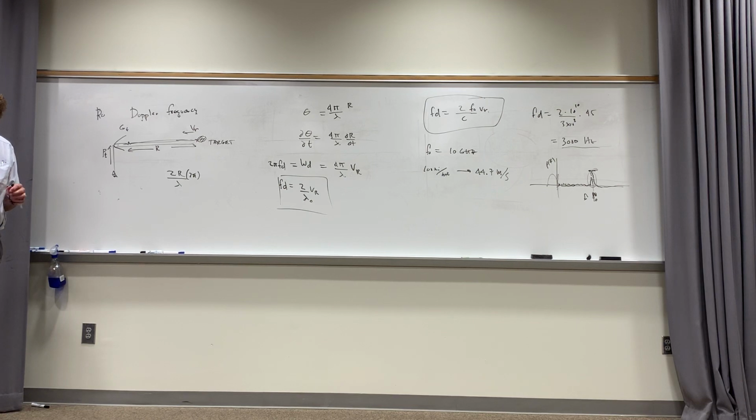And by the way, all radars of importance, I shouldn't say all, most radars today that are of importance are moving target indicators. They don't really care about how far away something is. Well, they do, but they really care about how fast it's moving at them, because that's the key. So moving target indicators are always looking at the Doppler shift, and that's why they're so important. Does everybody understand that? Keep that in mind, because people want to avoid problems.